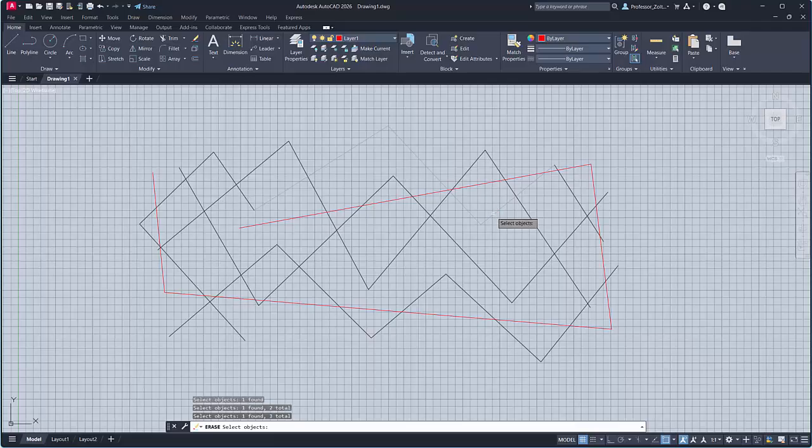So if I pick a line inadvertently, like I don't want to pick that, I've got a couple of options here. I can type in the letter U and enter, and it returns that line. U refers to undo. Well, what else could I do? If I click on that line and I don't want that one to be selected, I can click on that arrow that points backwards. That's also the undo command. But you'll notice that when I click on that arrow, it undoes all those lines. Why? Because one is a single step operation. The other one is a single command operation.